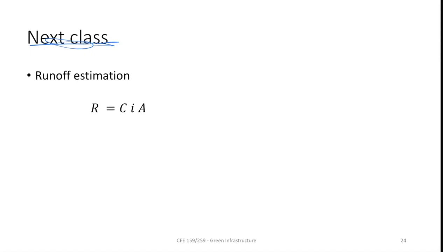And then there is a function C, which is a runoff coefficient, something that we discussed a few slides ago, before this class, that not everywhere the rainfall you receive is going to become runoff, because some of it will run off, some of it will infiltrate into the ground, a fraction of it will be evaporated, and a fraction of it will be stuck in the tree canopy as abstractions. Some of it will also get stuck in the ponds and all those other areas where they can capture water.